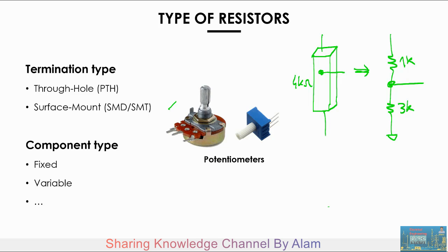If we go back looking at this potentiometer picture that we have here, it should be easy to understand why they have 3 terminals instead of 2. As we just said, we have the first 2 terminals, terminal 1 and terminal 3, for example. So the one top and bottom are just connected. Between them there is a constant resistance. And then there is another terminal, which is terminal number 2, the one in the middle, that is a special terminal that taps the internal resistor in different positions, so it can move up and down depending on the position of the knob. So again, the resistance between 1 and 3 is always constant, but the resistance between 2 and 1 or 2 and 3 completely depends on the position of the knob.